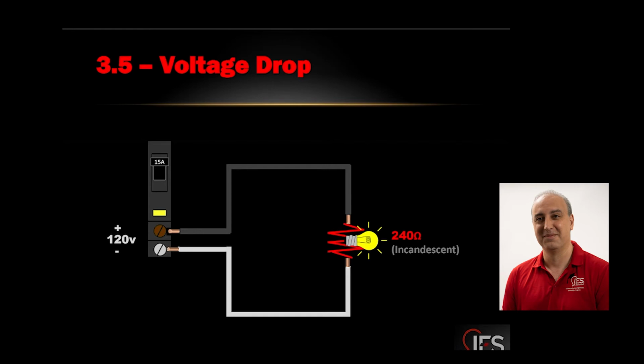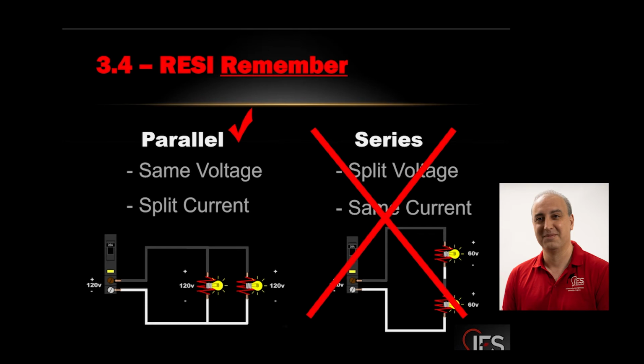Current carrying conductors, right. Yeah, remember, all conductors carry current. But when we say current carrying conductors, means under normal conditions. So the green or bare copper will carry current, but only if something went wrong. It's a safety line to trip your breaker. White and black, hot and neutral, ungrounded and grounded, whatever you call them, they're designed to carry current whenever you turn on equipment under normal working conditions. Go ahead.